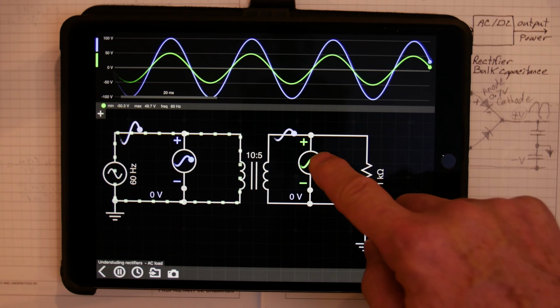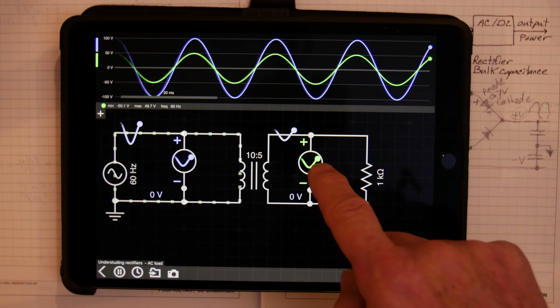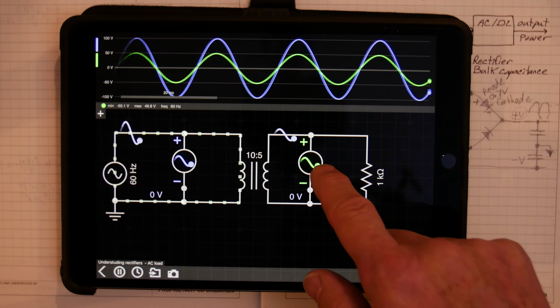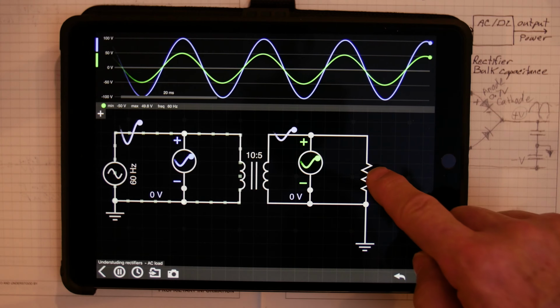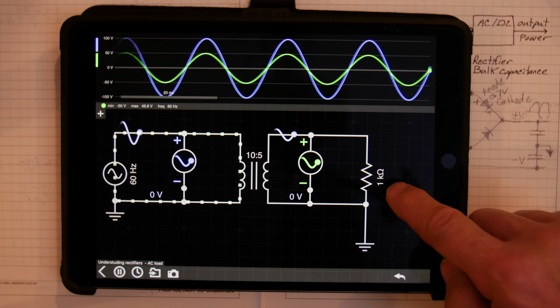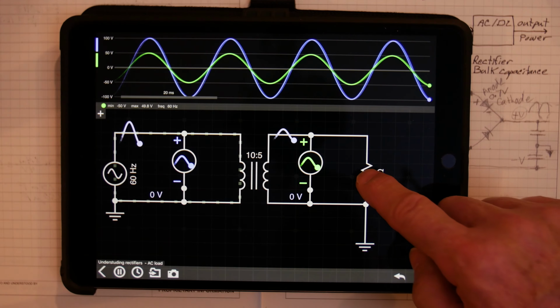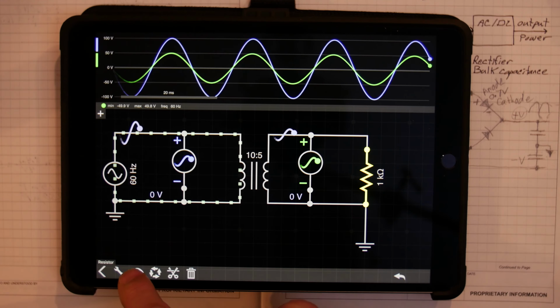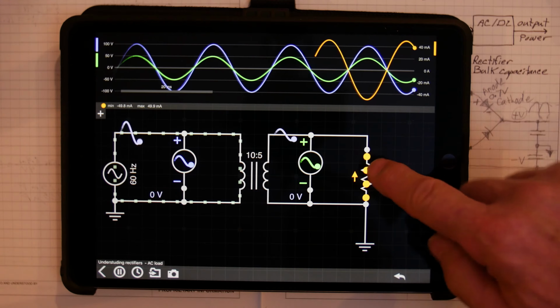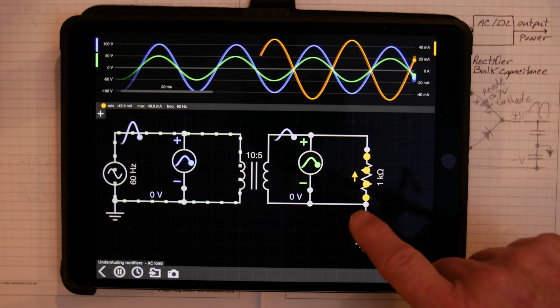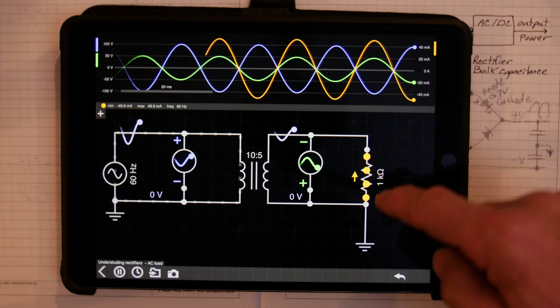Now, since we have an AC waveform like we do in our power supply design, we do want to rectify and change that to DC voltage for our load. This load resistor right now is a 1 k ohm resistor. Let's just watch the current that's in our load resistor. Now, see the arrow? It's pointing up. That's electron flow. We're watching electrons flowing instead of conventional flow.